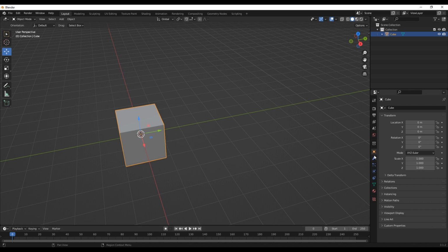So the next keyword is our properties or attributes, and that's what we have here. So here I'm in my object properties. So to create an animation, we can either do it here live, or we can do it in the property panel here by clicking any of these dots beside the property you want. So if I click here, you see that it has keyframed that, and then if you just go to our timeline, you see that it has added a keyframe here.